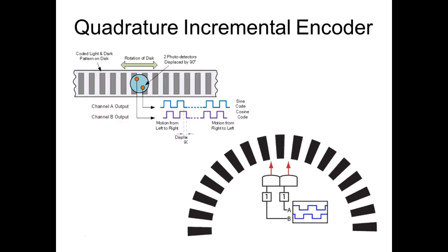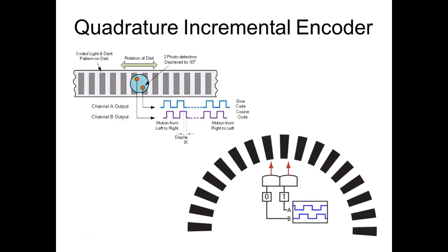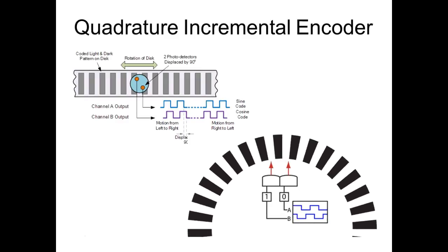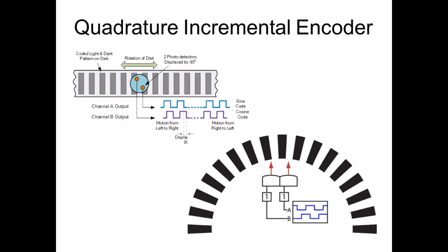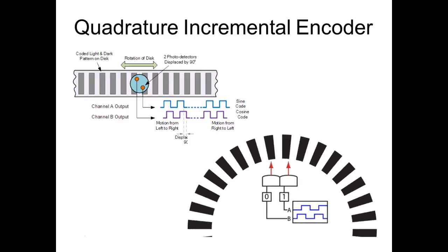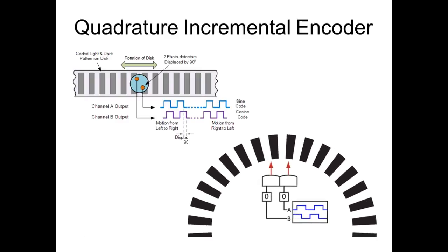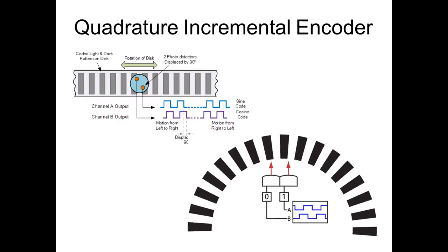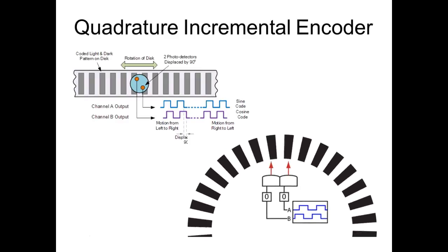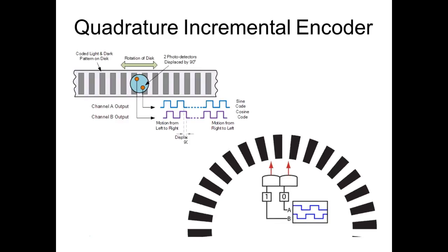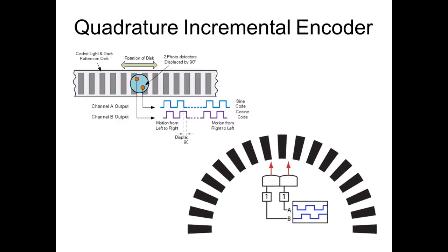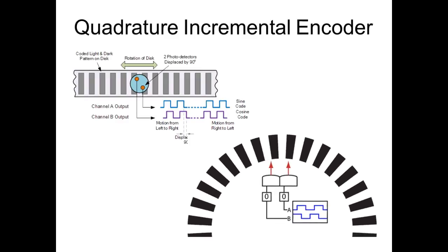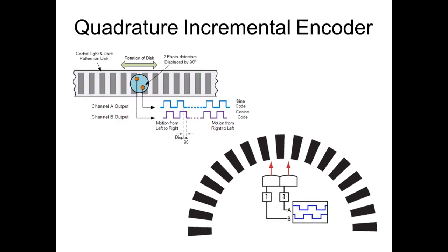So your inkjet printer, if you look at this, you got a alignment of little squirt nozzles on there, and it literally just squirts out little drops of ink and creates characters with what? With dots. Yeah. Now, normally now they're really, really close together. The first thing we had was a 7-pin printer, and it couldn't do descenders. It couldn't do lowercase y's or anything like that. So everything was shifted up. And then they came out with the 9-pin dot matrix printers, and the only thing it added was the ability to do what? It's what we call descenders, which would be lowercase y's, lowercase g's, that kind of stuff. These characters that have to go below the line.